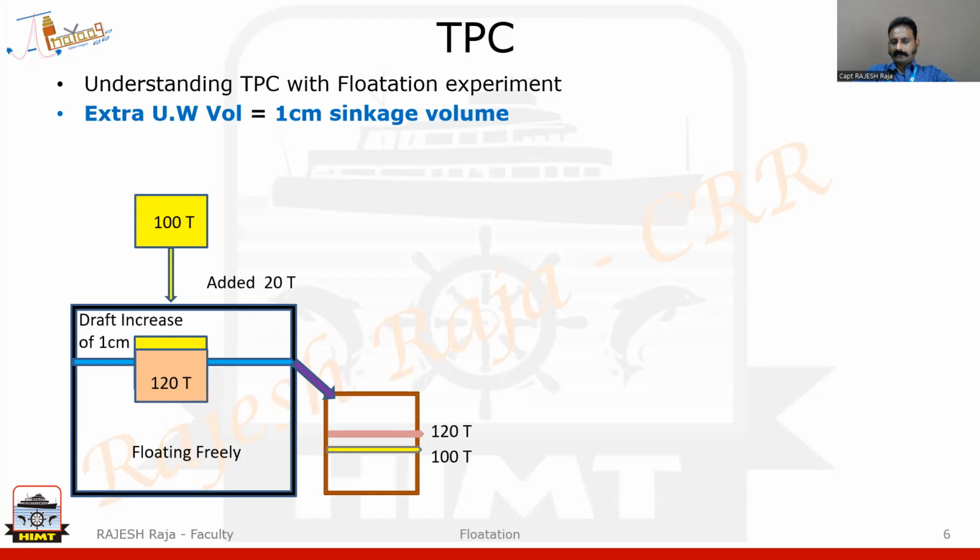So that extra which you overflowed can be calculated as the length into breadth of this particular vessel or object. Okay, that is the water plane area for that vessel, because I've shown you a rectangle, which is very easy, length into breadth. And the extra depth you got was exactly 1 centimeter.